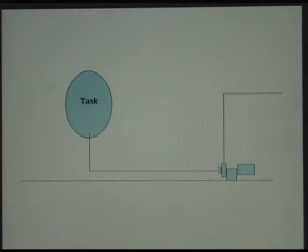But if you can't design your process to do that, then you end up with a flow element and then a recycle valve that would just continually have fluid traveling in a big loop to keep the pump operating at the correct location on its performance map. Now one would ask, aren't we generating a lot of heat inside of this loop? And the answer is yes, but heat generation inside a pump is not as fast or as great as inside a compressor, and so you can operate like this for great lengths of time without building up a tremendous amount of heat inside your process loop.